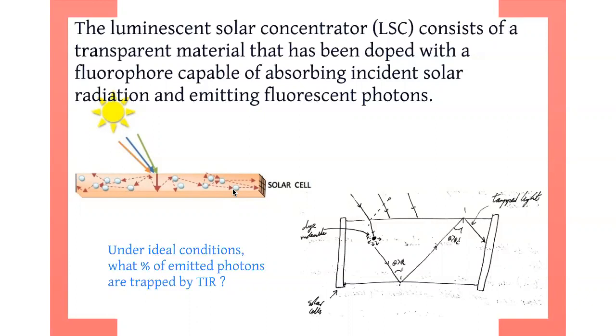How would I increase that, by the way? How would you minimize this loss? Any ideas? You can roughen the surface, which is a good point. That will do light trapping, so you will trap more of the light. But there is a problem here in the sense that if you roughen the surface, it won't be transparent as a window anymore. It'll look like frosted glass, which might be okay for some applications. That's a good idea. Anything else just from looking at this?